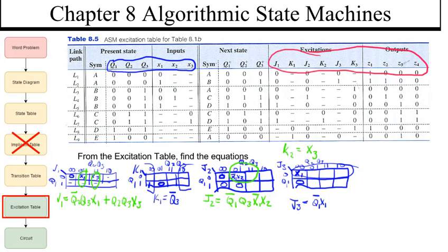K3 is going to get complicated. We have 1, 0, 0. We're trying to collapse those into what? It's going to be a combination of x1 and x2. Can we write that down? Not x1, not x2. Right. Okay, so we can write this one down. 0, 0. That's going to be easy. So we can do this in the same way we've done these others. So K3 right here is going to be not x1, not x2.